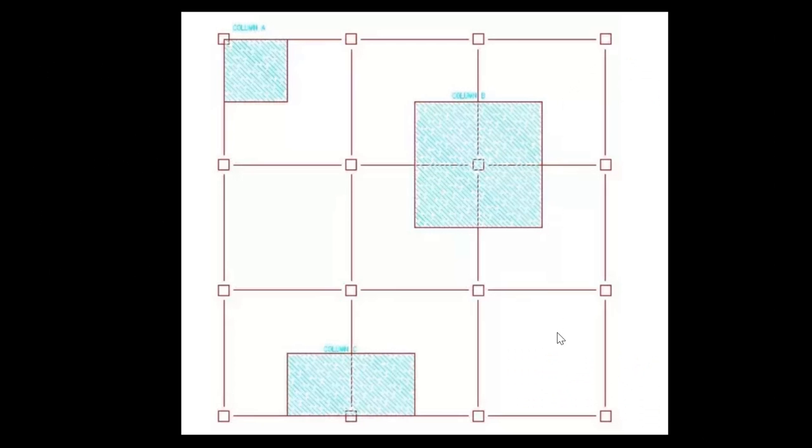The second one you can see here, the load in this direction is balanced, but here you can see there occurs a bending. There is an eccentricity of load over here, because the load will be acting over here. As a result, there will be bending in one direction. Here this corner column, you can say there is eccentricity in this direction, there is eccentricity in this direction, there is no balancing of the load. So this is a column with biaxial bending. So I can say every corner column will be having biaxial bending. Every edge column will be having either uniaxial or biaxial bending, and interior columns, with the loads and materials used being same, will be axially loaded.